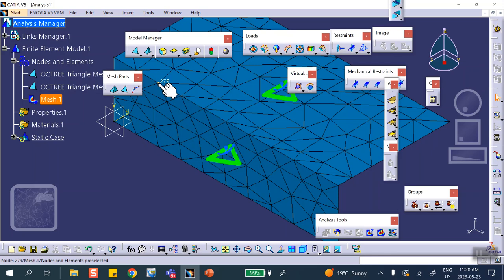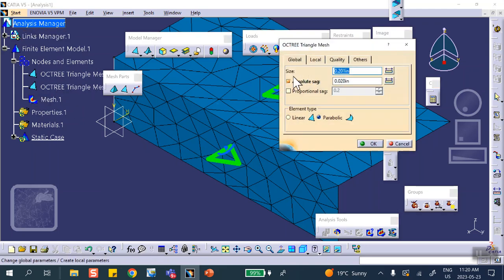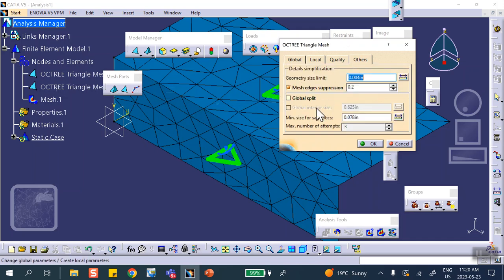Of course, it's possible to come and fix this, create a connection between these, and make that some kind of a rigid connection or fastening connection. And we're going to do some of that later on, but this is not going to do it. The alternative would have been, when I mesh this thing, it is possible to go to the advanced meshing tool.